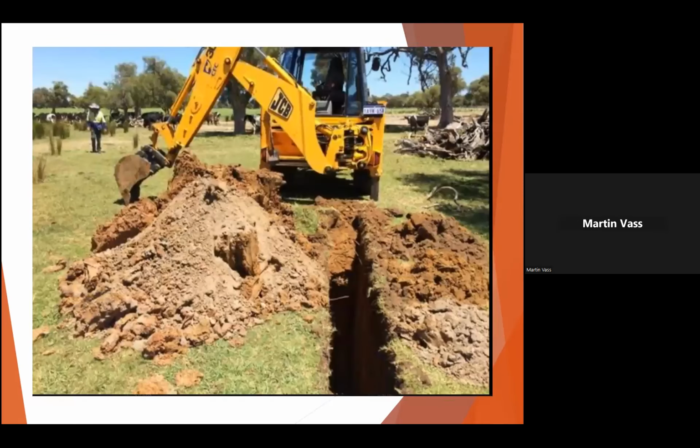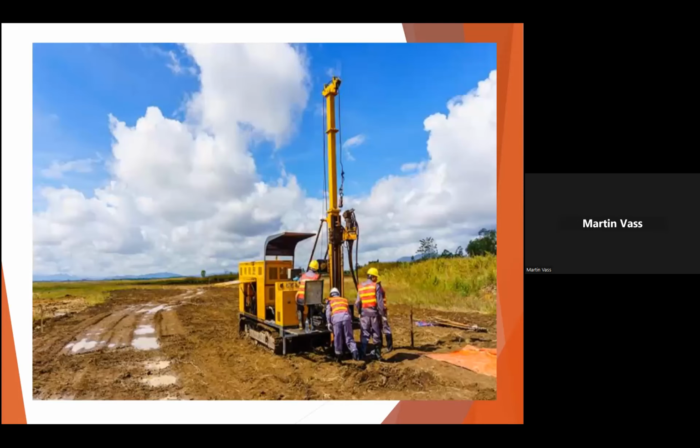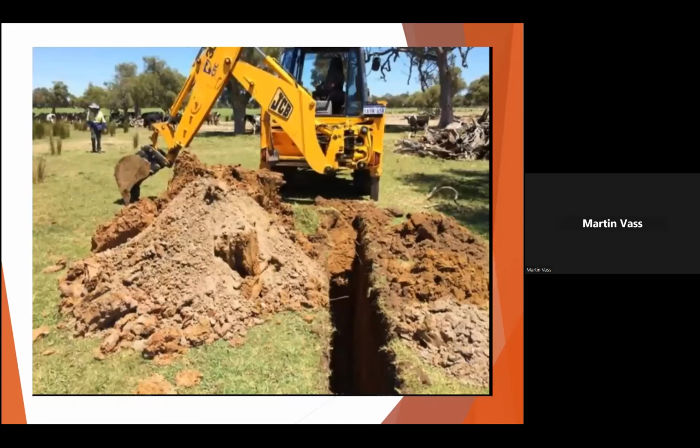You either do a core, which is taking these cores, or you do an excavation and you then map. You do an excavation, you then go into that hole and you map the material in that hole. And all this information is given to the engineer, who's then going to do the design of the foundations.